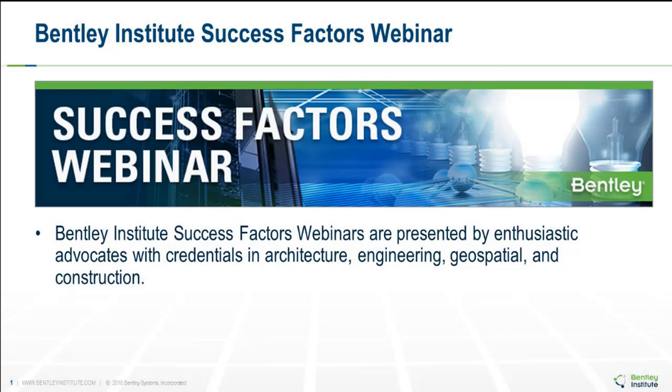Thank you. Next question. Can ground control points be added to the mix in order to get a model that is 100% to scale? Yes. So ContextCapture features a ground control point editor in which you can import your ground control point coordinates and do measurements in the photos. So this will ensure you really good georeferencing and perfect scaling of your 3D mesh.